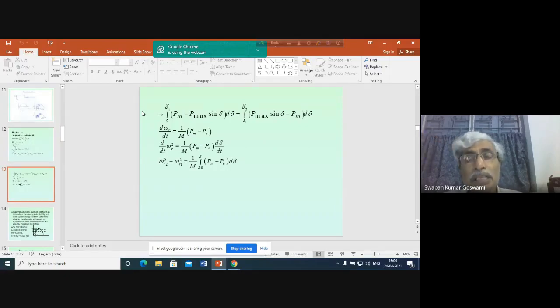That is called the infinite bus. So infinite bus basically represents a very large generator with infinite capacity. If this is the situation, then there will be no other oscillations present in the system, and under that condition only the equal area criterion will be applicable.